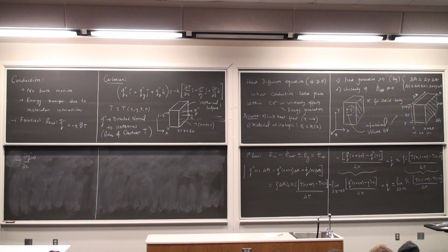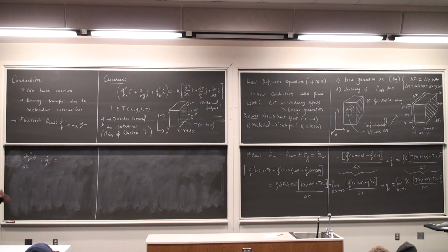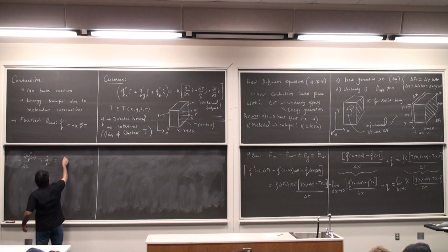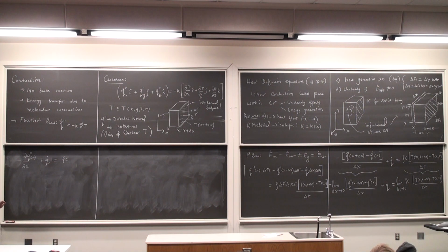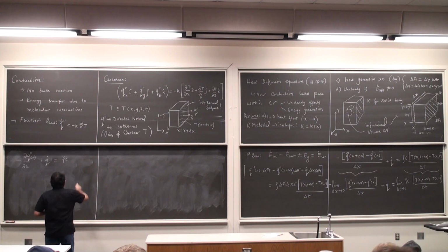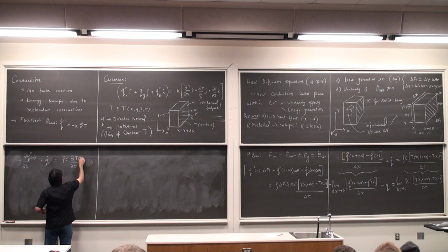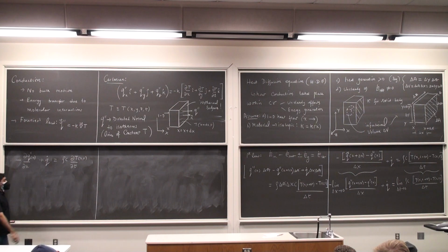They will come soon. Plus Q dot. And likewise, rho times c is a constant, does not get affected. And I'm going to have limit of T minus T at two different time instances divided by delta t, which is dT by dt, the partial derivative of temperature with respect to time. Temperature here is a function of x and t, which is why we are taking partial derivatives.